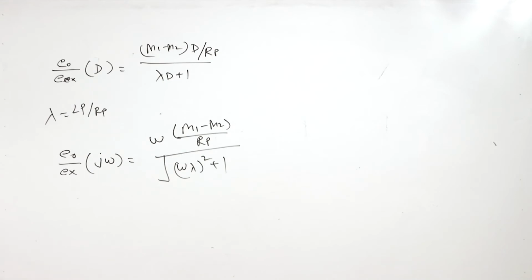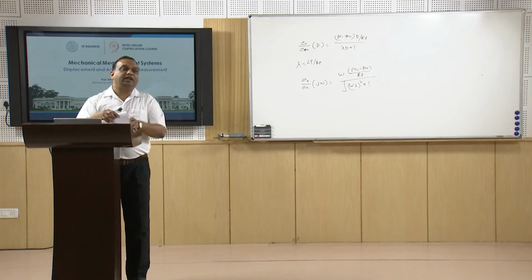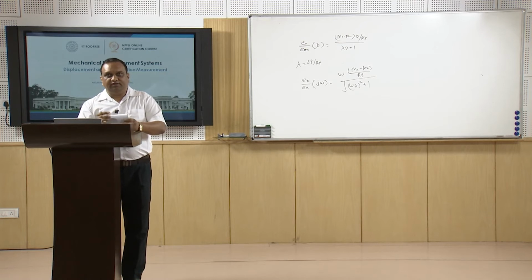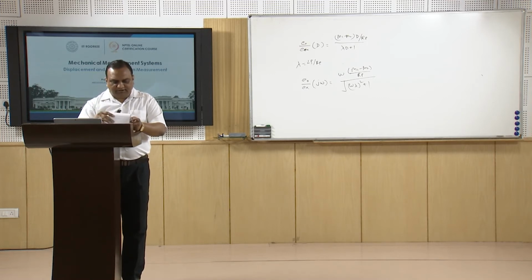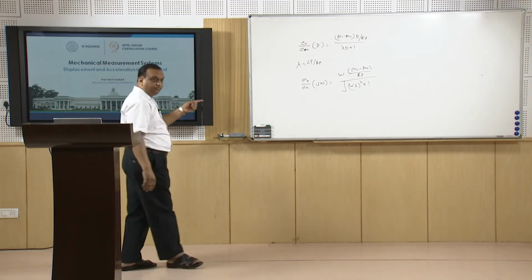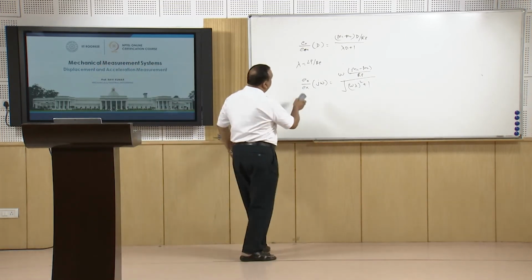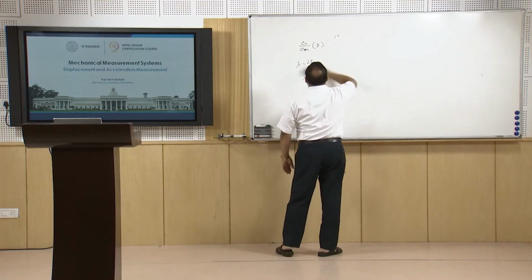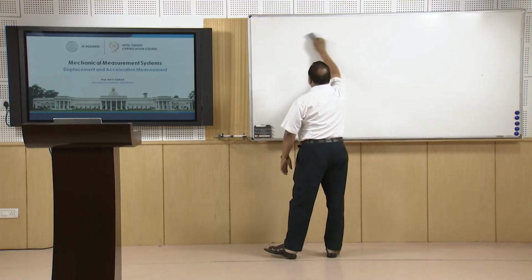Now, LVDTs have a variety of applications, right? And the best part of the LVDT is it can accommodate a very high order of displacement if you compare with the potentiometer. And linearity is another benefit of using LVDTs. So after LVDTs, we'll go for the capacitive transducers.